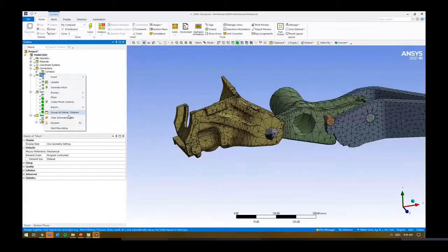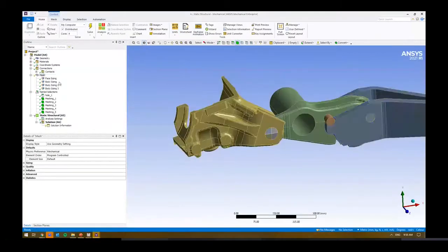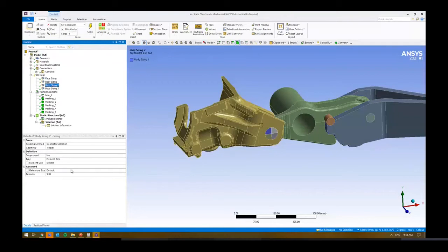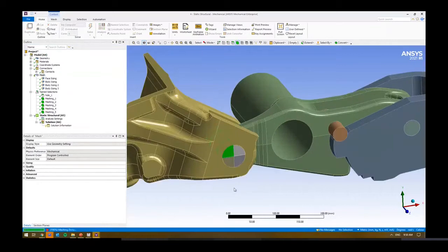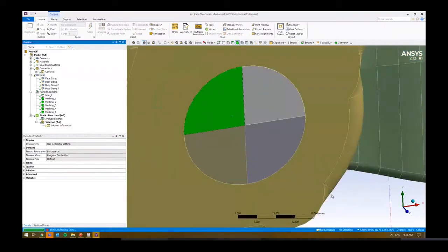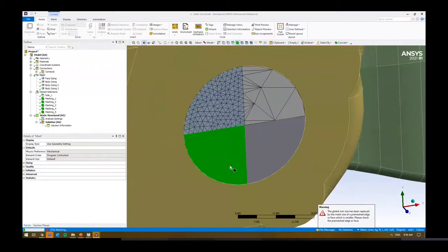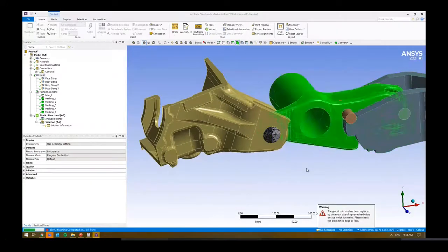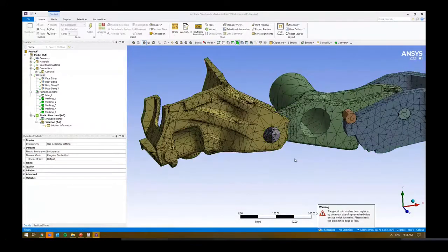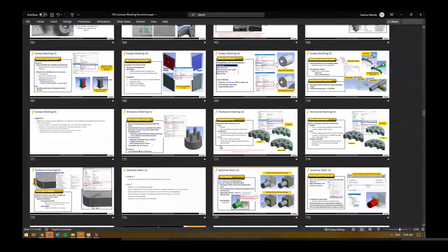Now the benefit again is if I did want to go back and let's say I make some changes, this sizing instead, I want to make this 2 millimeters, right? Right click, generate the mesh. You'll notice it'll generate that first, right? Because that's exactly what we asked it to do. It will then generate the mesh on the right. It'll generate the mesh underneath, generation one on the bottom right, and then go through the process of generating everything else as well, right? So if you've got some complicated geometry that requires a couple of steps, you can use that functionality in there as well, right?